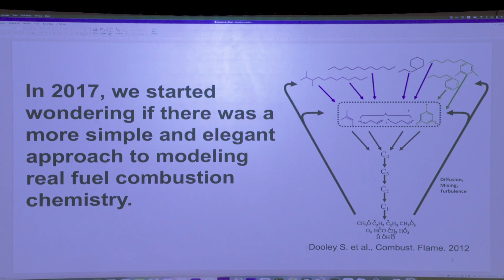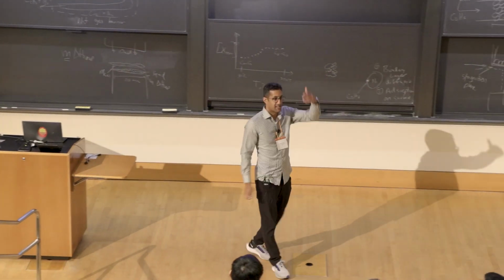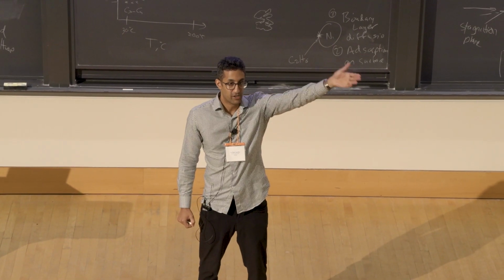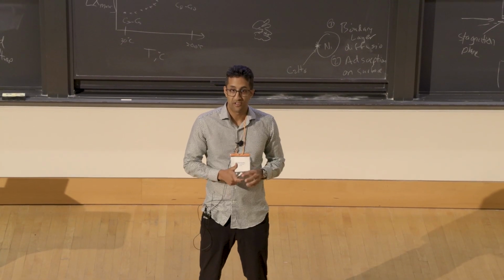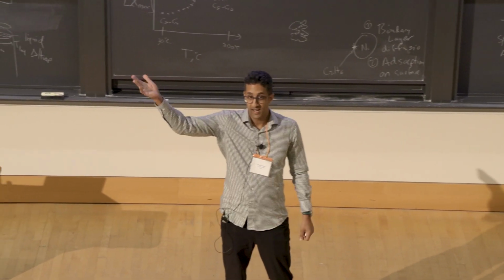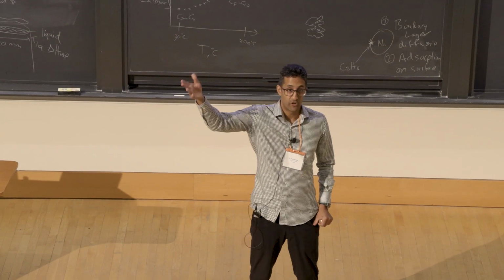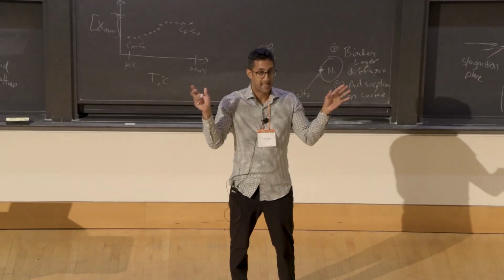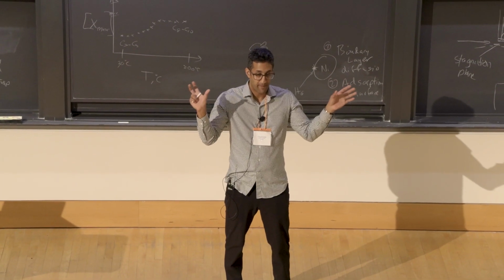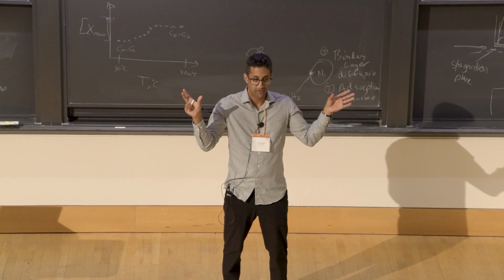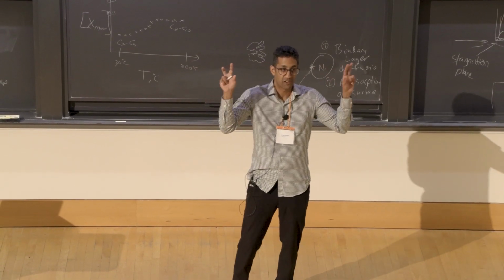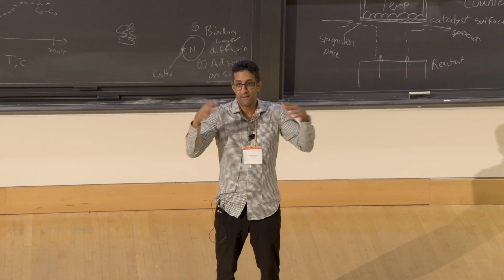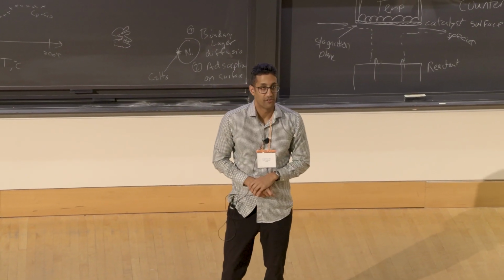And that explains also why a gasoline that has an octane number of 97 and a motor octane number of 87 in the US, which has a very different composition than a gasoline which has an octane number of 97 and a motor octane number of 87 in Europe, still behave the same in the engine, yeah? And that explains, even though kinetically the components might be very different, they have similar octane numbers, and that's all that matters. So somehow this measurement of octane number has been done at a condition which makes fuels behave the same way in the engine, even if they're different compositions.